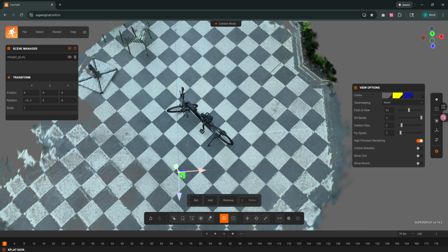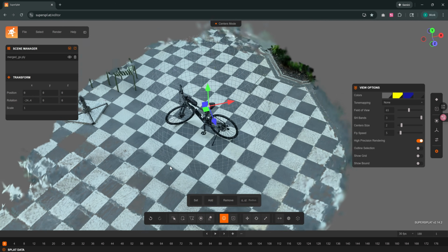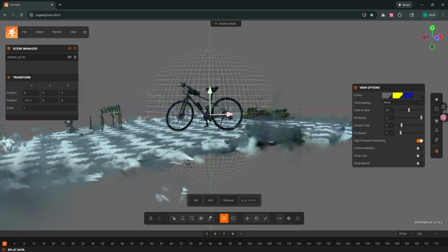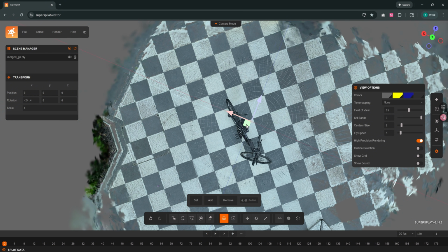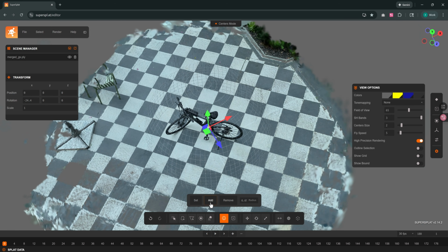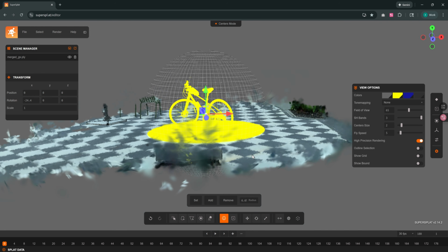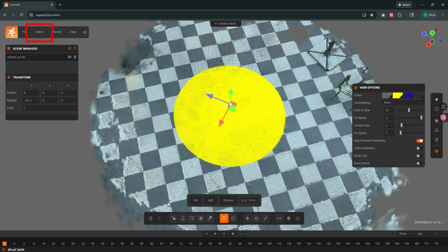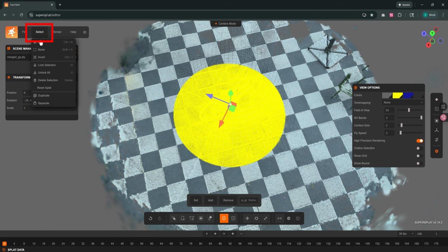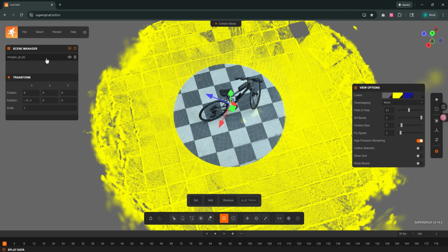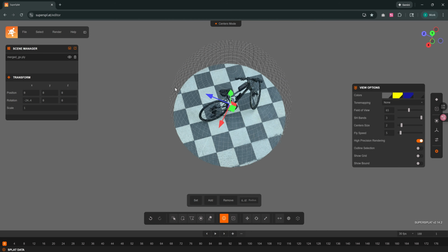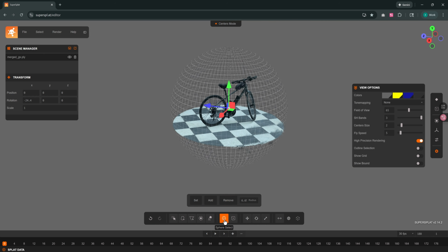Finally, for 3D control, there is the Sphere Select. When you click the Set button, a sphere will appear. Then adjust its size and position to select everything inside that volume. Click Invert Selection in the Selection menu to select all Gaussian ellipsoids outside the sphere and delete them.